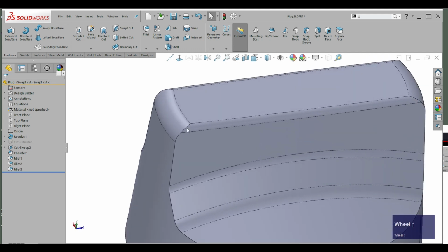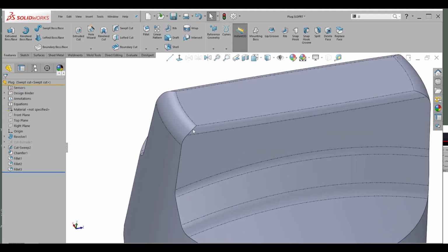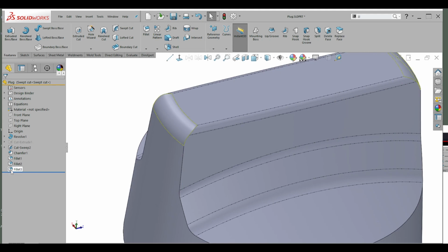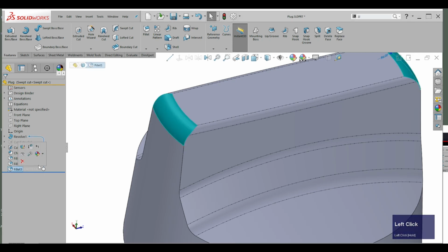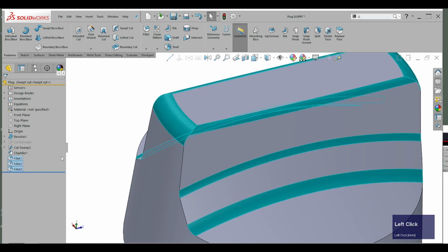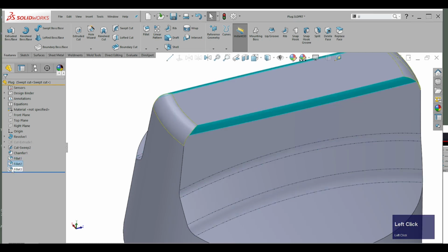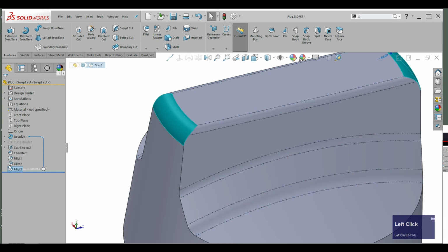But you can see that it has not created a nice edge over here. So if I want to, I can just drag within the feature manager, which is a very powerful feature, which we'll talk about more later on. As long as I click on the icon and not on the name, although the name might also work. Sorry, yes. What I'd done in class is I'd done a drag select. If you drag select, you select a whole lot of features. And what I meant to do is click, drag, select. So I'm going to move the one feature above the other.